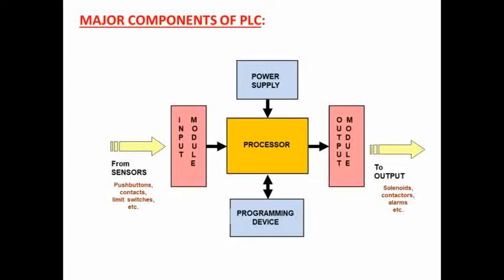Thirdly, the input module carries out electronic isolation, not electrical isolation, by electronically isolating the input module output from its input. Finally, its electronic circuit must produce an output via output logic to be sensed by the PLC CPU.